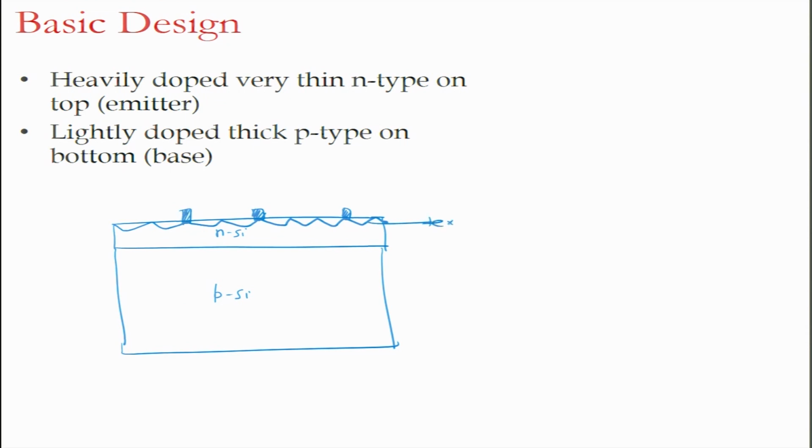So, this is a textured surface to maximize light absorption, because you will have some internal reflection, and on top of this we have an anti-reflection coating. So, on top of this we will have an anti-reflection layer. This is a typical device design, and on the back we will have an electrode here. This is the back metal, this is the top metal.